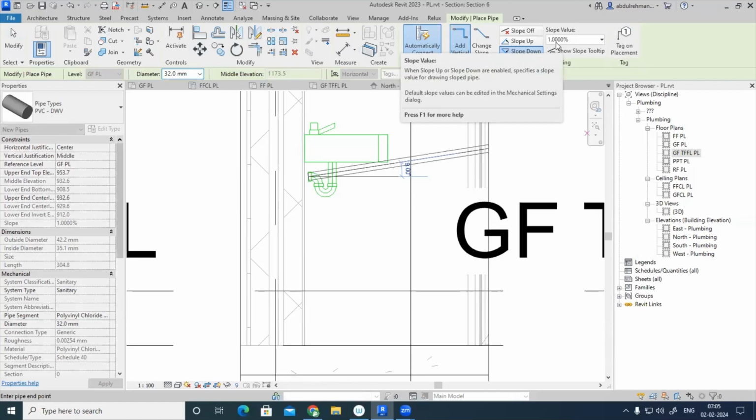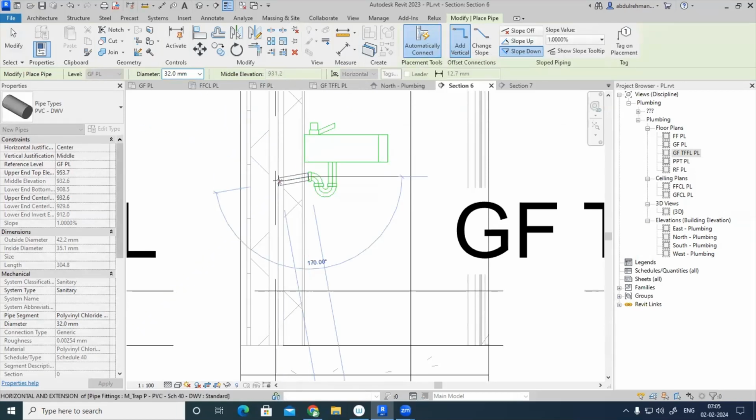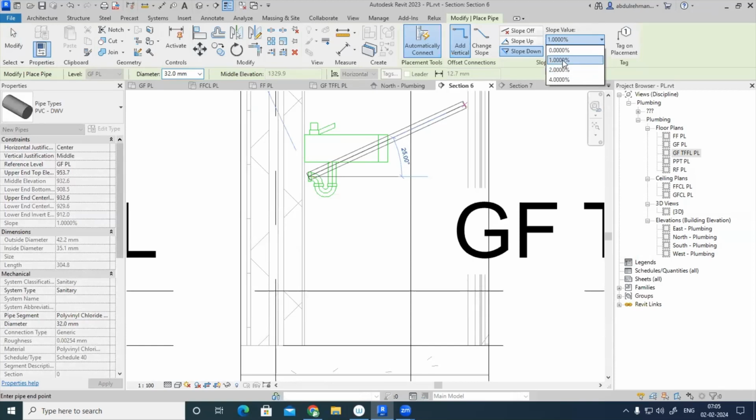So as per the standard your company is following or the country is following, accordingly the slope value has to be adjusted. So if you want, you can go for 1% slope, or if you want, you can go for 2% slope. Okay, depends. So whether you are following IPC, like a 2% slope you have to provide, or if your company is following 1% slope inside, you can follow 1%. IPC, a pipe diameter up to 2.5 inch, you should follow 2%. Otherwise, you have to go for 1%. In a lot of companies, they might be following 1% without any standard. But okay, that is totally dependent.